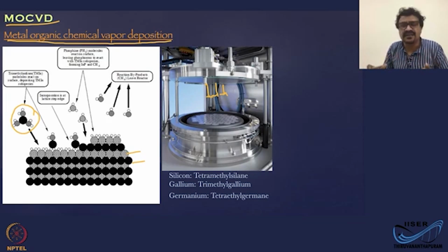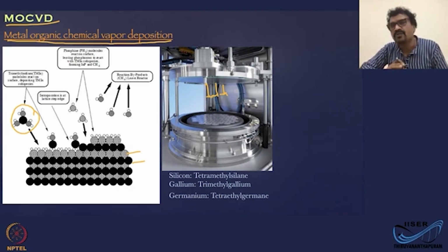But for commercial scale fabrication of heterostructures, for example for applications in light emitting diodes or all kinds of other optoelectronics applications, like your computer screen, those are all made by CVD, or the MOCVD process, because you can grow large area heterostructures with relatively very good uniformity.